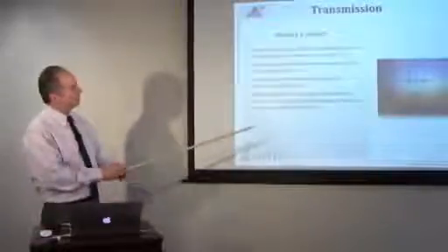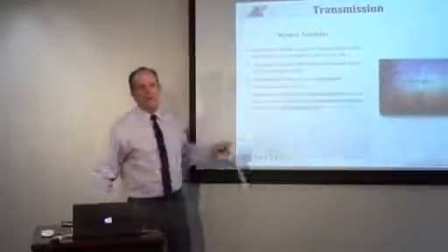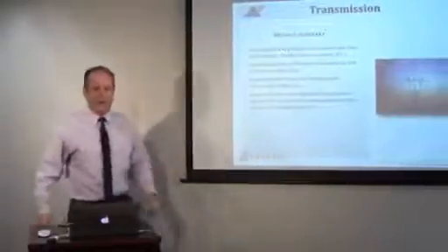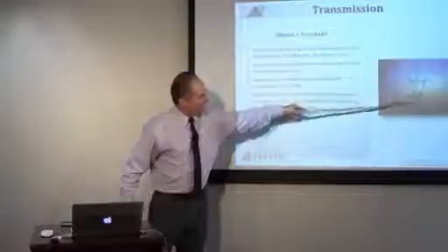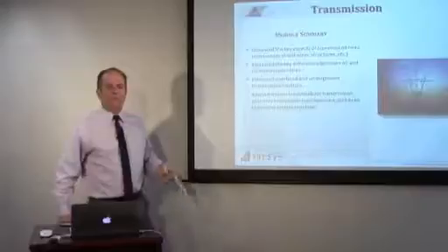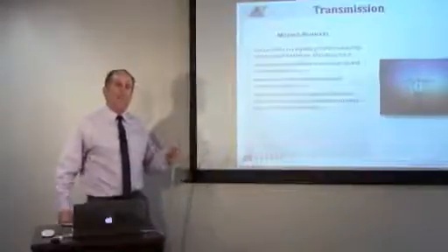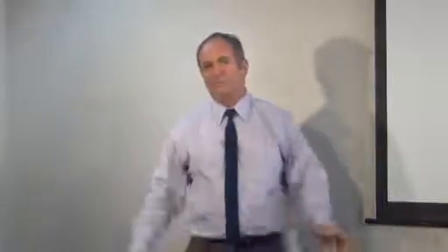The one thing I would like to add that I see didn't have a slide for is the static wire up on the very top. And you can see it in this picture here. On the very top is a static wire, sometimes called a ground wire, sometimes an earth wire, sometimes earthing wire. But the idea is a static wire is connected to the structure, which is grounded, so that lightning is attracted to the static wire. So if a lightning strike hits the static wire, that lightning energy will go into the towers, usually 2 or 3, depends on the magnitude of the strike, and dissipate into the earth.